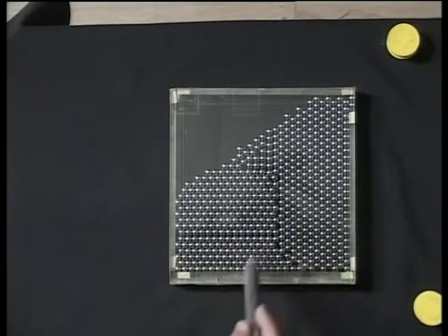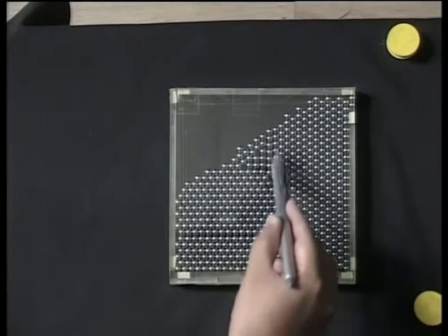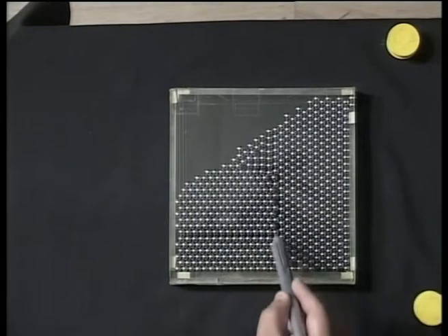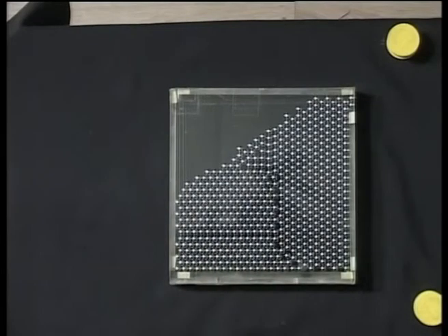Between these 3 regions, of course, you can consider some disordered region here. Within these 3 main crystalline regions, you can see there is a boundary. This is what we will soon define as a grain boundary. So you have a grain boundary which goes like this. This is one kind of defect which we can nicely simulate using this toy model.